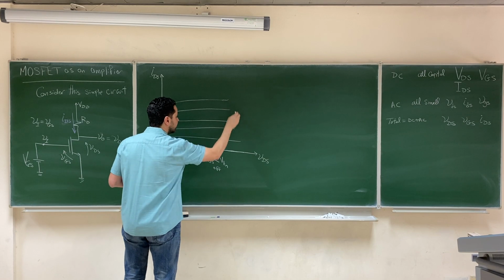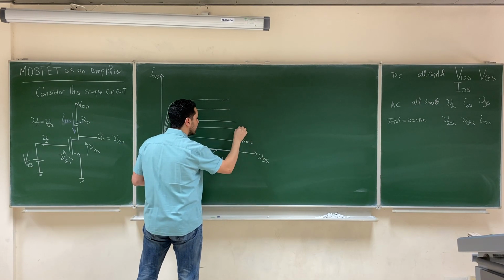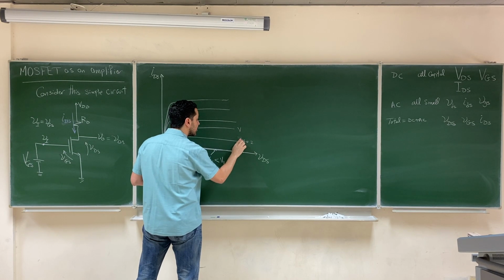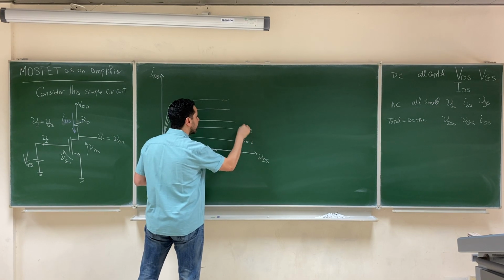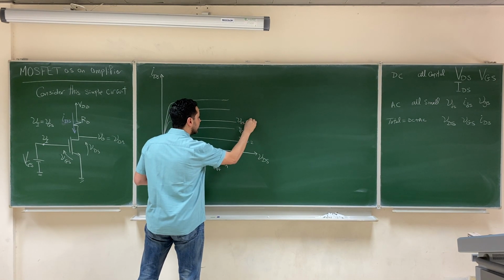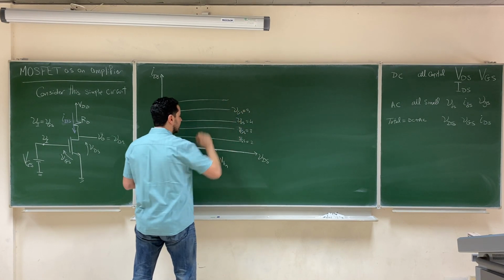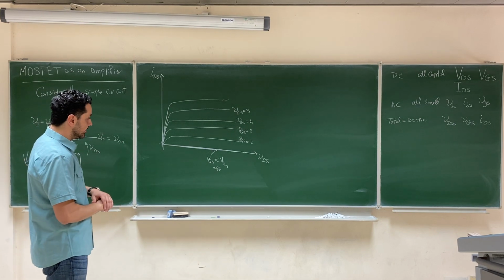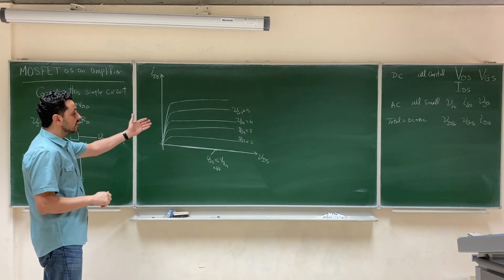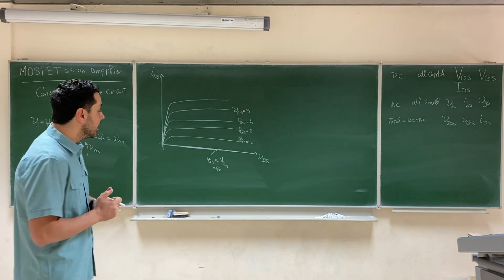And then as you increase VGS, you start to get curves like this with a saturation region and a triode region. So as you increase VGS, let's say this is VGS equals 2 volts, and let's talk about the total in general, so small v capital GS equals 3, for example. I'm giving just these numbers as examples. And so on. So you will get a set of curves that look like this. This set of curves comes from the physics of the transistor, right?